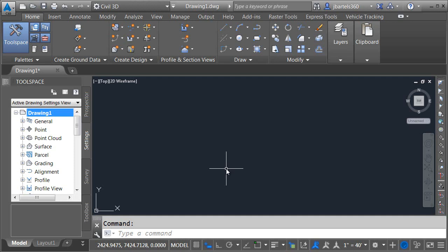a swept path analysis. As you can see, I've just launched Civil 3D 2015, and I'm sitting in the default unsaved drawing file. Now, even though this file is unsaved, it is based on the Civil 3D Imperial template, and in that template, each unit equals 1 foot. Since we're going to be talking about scale here in a minute, we'll verify the units in this drawing.